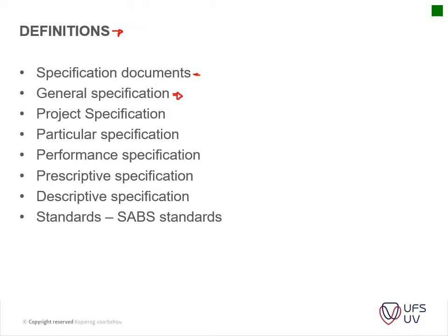It's located, for instance, in Bloemfontein, in Langenhoven Park, where you have prevailing clay conditions, in comparison to maybe Universitas Rif, where you have a hard type of excavation, where it's not really clay material but harder material to excavate, and thus you do not have to import that much material when doing foundations.